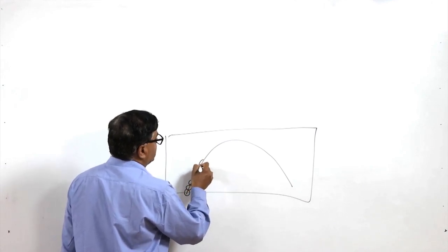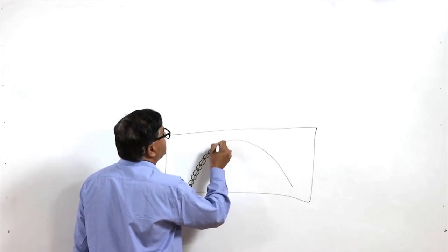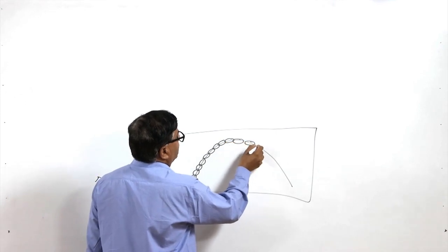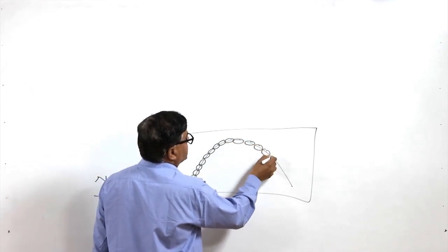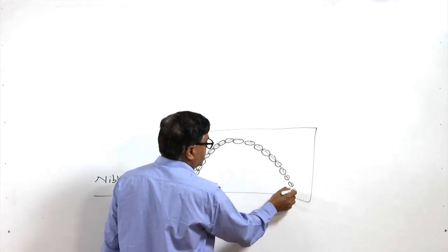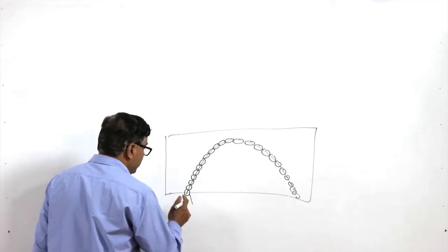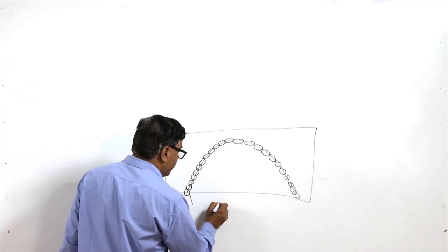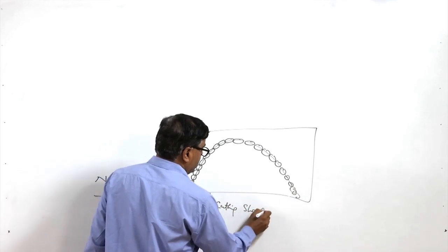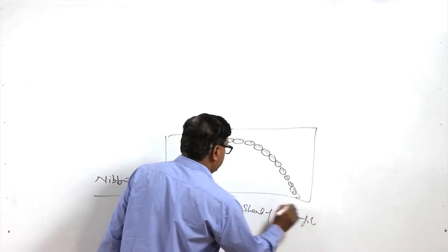This is basically shearing, but successive shearing is carried out along a particular line so that a strip in a desired profile can be produced. This kind of operation is called nibbling, primarily used for cutting the sheet to a specific profile.